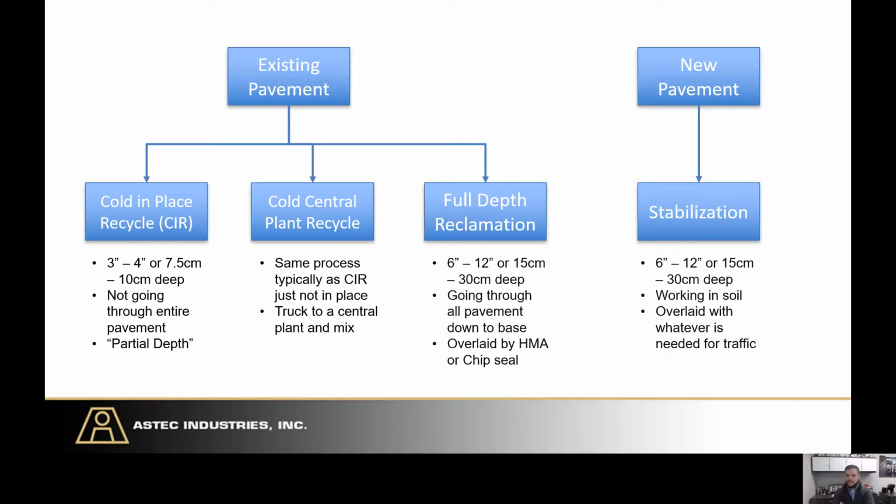So new construction is going to be more in the stabilization realm. If we're recycling or reclaiming an existing pavement, then we're usually looking at cold in-place recycle, cold central plant recycle, or full depth reclamation. And there are a few significant differences between these processes.